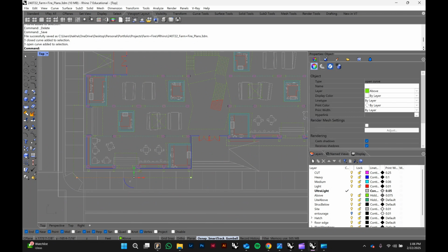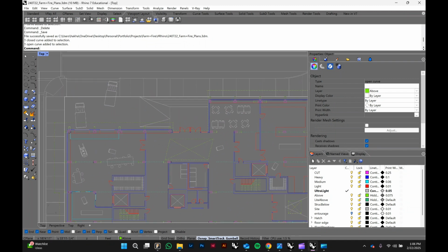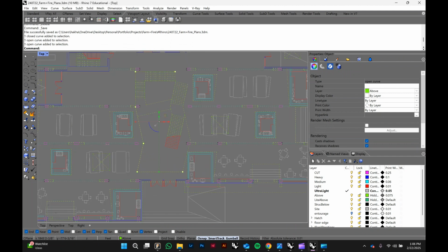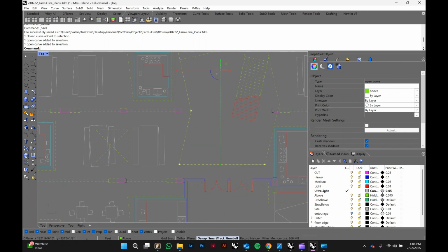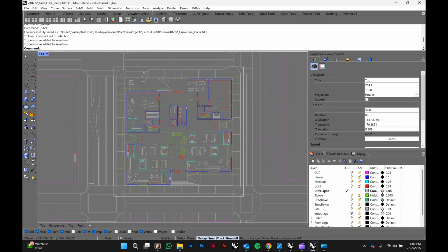So for example, like this above cut line where my building kind of overhangs, that's a separate Make 2D I've made to get that layer of information. As well as here in this sort of atrium space, how there's a cut above the floor plan. So keep in mind that the Make 2D is a tool to help aid you in making your plans, but it's only one step in the process. You still have to line weight them and add in entourage and site context to really make your drawing speak and sell your story that you're crafting.